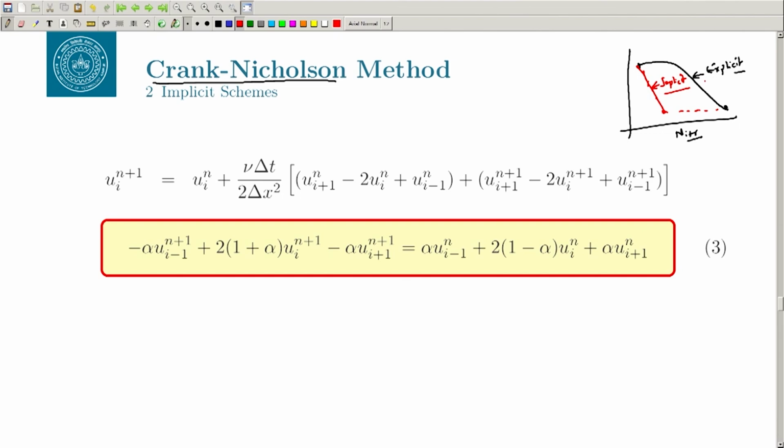But there are physical considerations, what is the delta t we should be using, what is the maximum Courant number that should go, right. But typically, for example, in explicit, if you are limited by Courant number less than 1, you can easily go in for the implicit scheme, for example, Courant number less than 5 or less than 10 and so on and so forth. Okay.